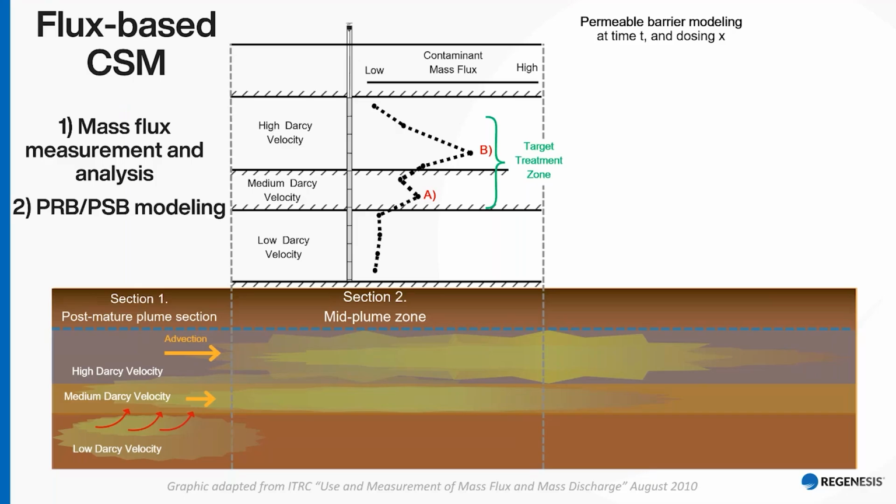So how the contaminant incoming mass flux, once it hits the barrier, what is going to be the dynamics, what are the byproducts generation, and of course, over a given period of time, certifying that there is not going to be breakthrough over this period of time. And for that, we divide it into two peaks. So for peak A, this is a barrier thickness, and you see this shaded area where the PRB will be emplaced, and there is an incoming mass flux.